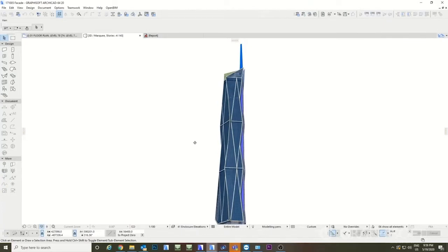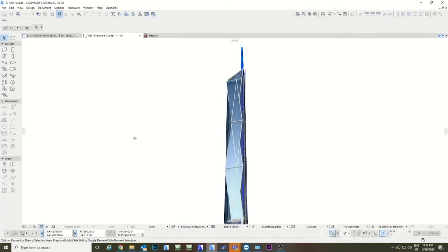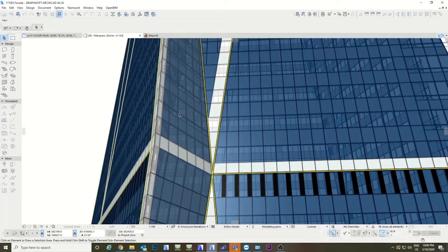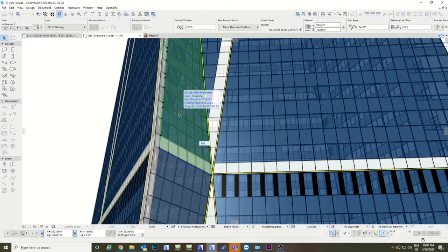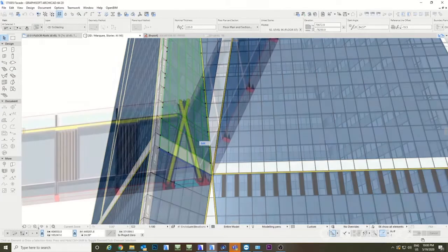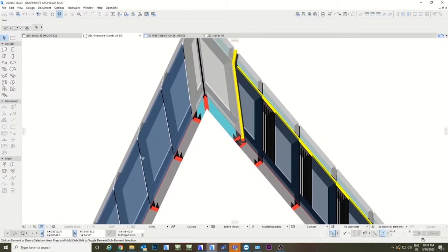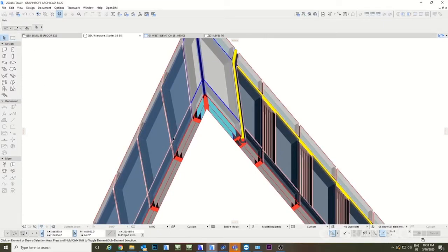It's got 3 outrigger zones. That's where, you know, major pieces of steel come into the concrete core and anchor and help support the building. It's got complex shapes. The curtain wall is crystalline, it moves, it has to meet the concrete accurately. The concrete has to work, in a sense, coherently with the core and the steel structures.